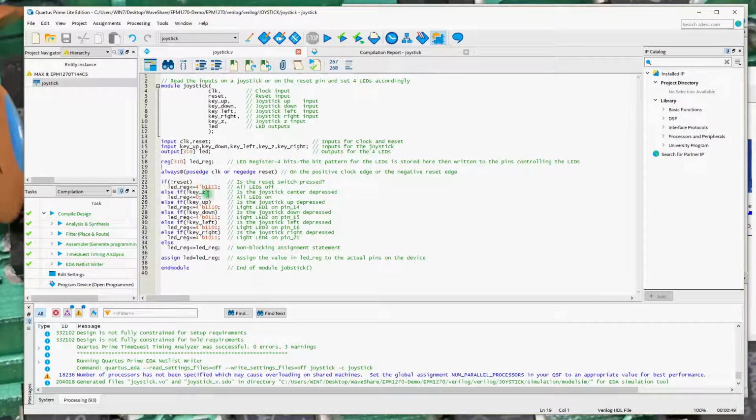So this just chugs away there. Normal execution, every positive edge of the clock, this happens. If you push the reset button, that will force a reset, and on the negative edge it'll also happen. And if it's reset, of course, it'll turn all the LEDs off. So hopefully this explanation helped a little bit. It's helped me work through this and understand a bit more about Verilog.